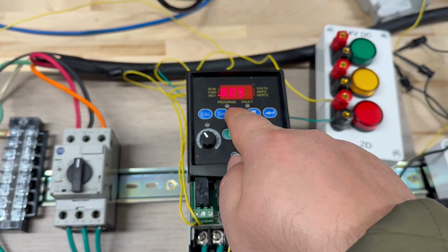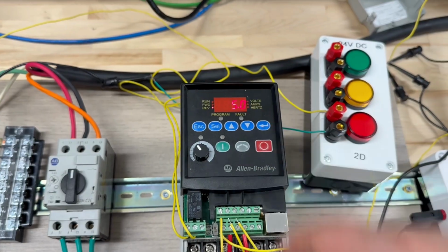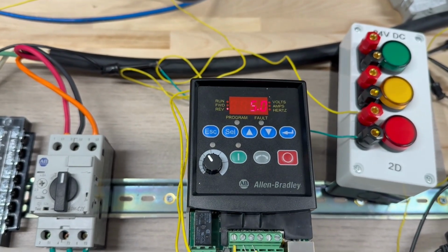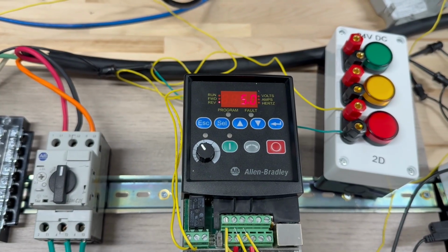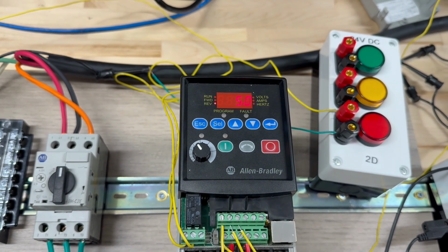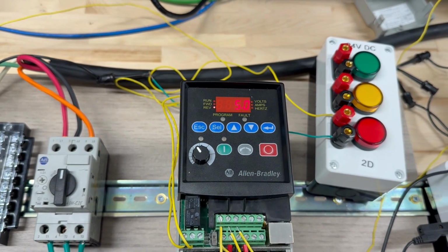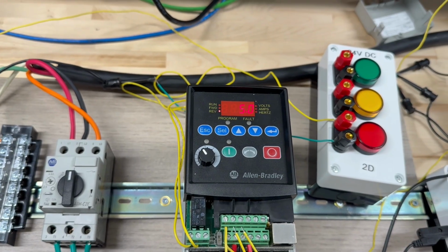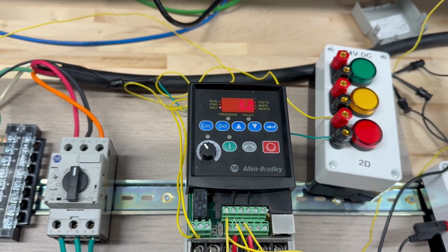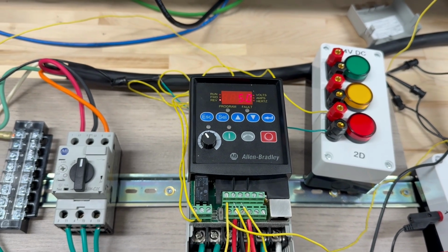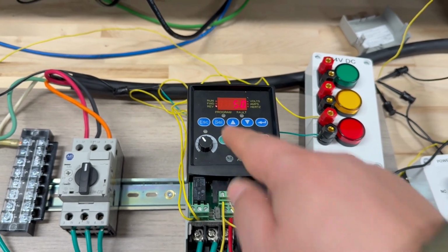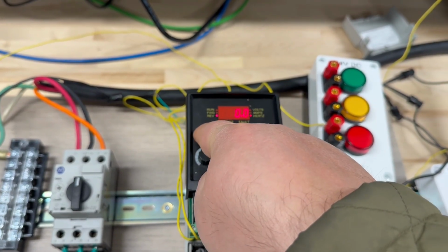Now in 93, the time delay between each reset: whenever you get a fault, wait 5 seconds. You can adjust that; I adjusted it to 5 before. So give a 5 second delay, then retry a total of 2 times. If you fail again, you turn on the light. Looks fine.